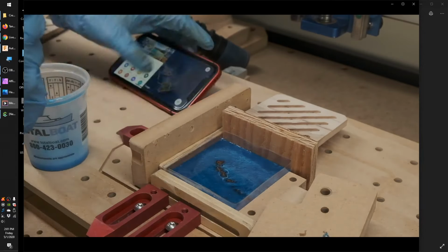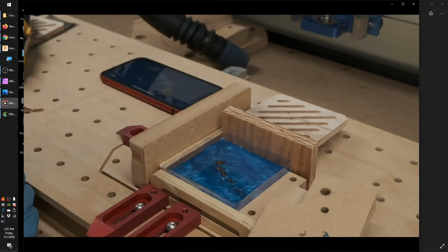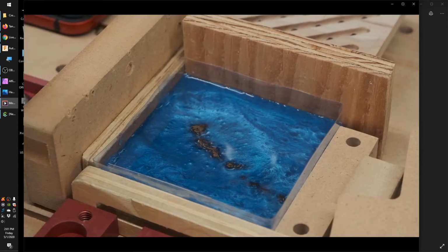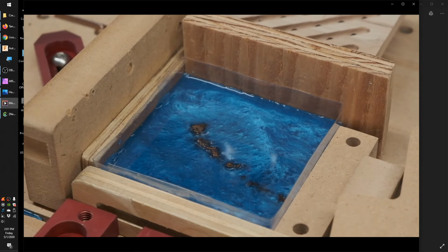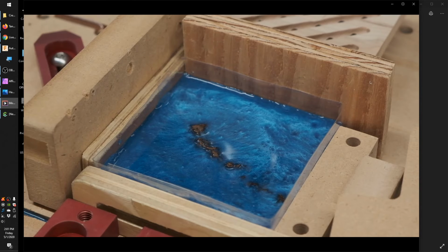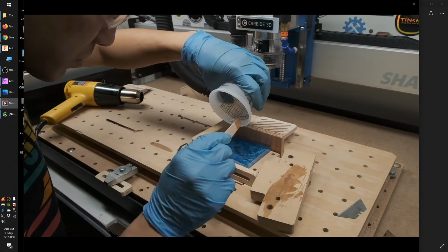And the interesting thing about epoxy is, as it settles, as that meniscus forms, or as height variations even out, you get convection currents in the epoxy. So if you want to do artistic swirls, you want to wait a couple minutes afterwards, as the epoxy settles out, and you can leave in whatever swirls you want.